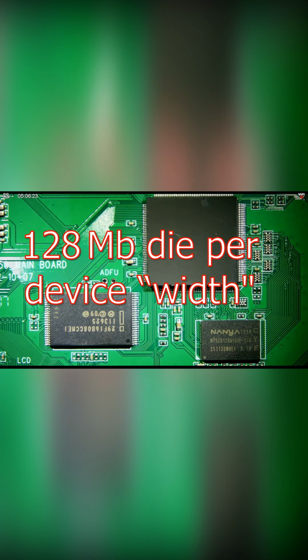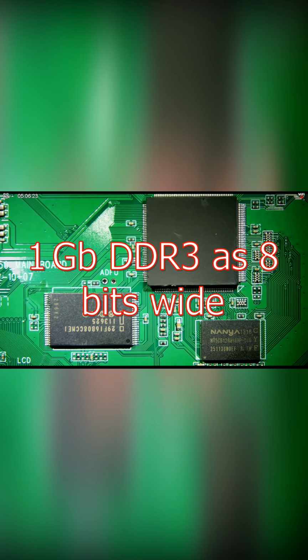So this Nanya chip is a DDR3 SDRAM part. You can tell because of the large part number identifier. Inside that number salad is the telltale sign, 128M. This portion usually indicates a 128 megabyte die per device width. So this chip typically provides a total density of 1 gigabyte of DDR3 when it's organized 8 bits wide, as this chip is.